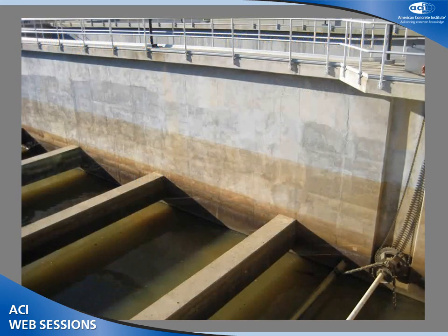And you can look here, this is a treatment tank, and this is some equipment that's used for taking the sediment out. But we may have varied water levels. One of the most aggressive conditions is where you're right at the water-air interface, and it's actually going up and down. Tends to be very aggressive, as well as having the exposure of the water with chemicals in it. And then you move to wastewater with sulfates, industrial chemicals that get into wastewater treatment. Even municipal wastewater generally will handle some level of industrial chemicals.